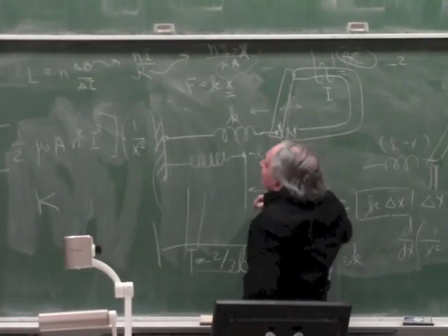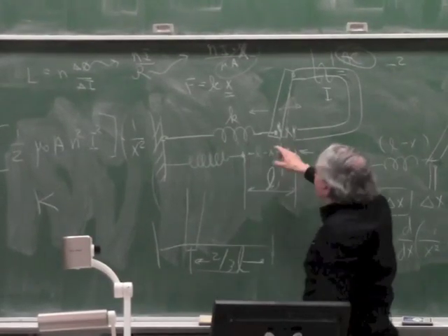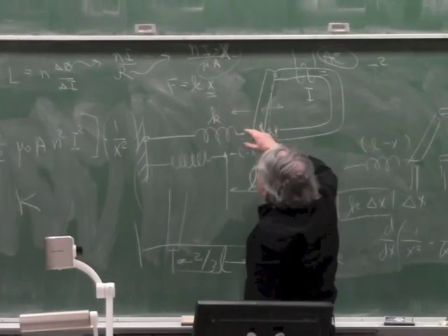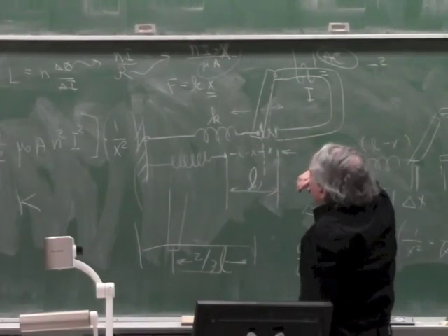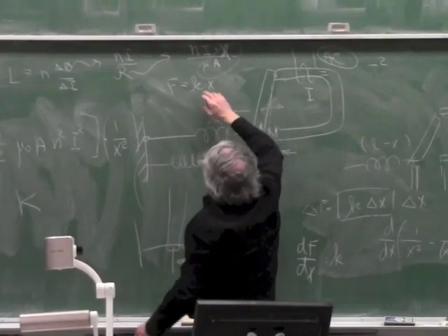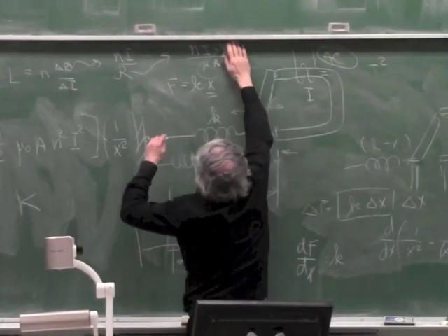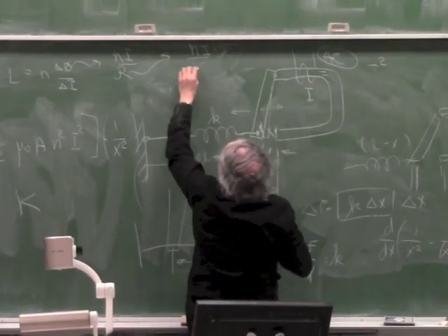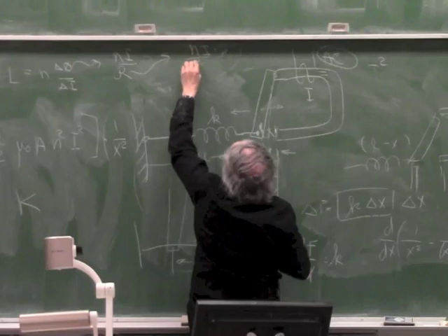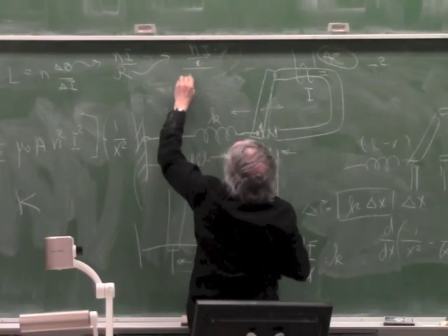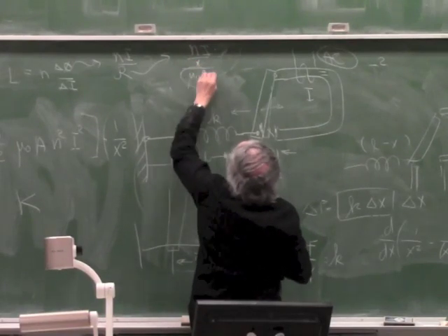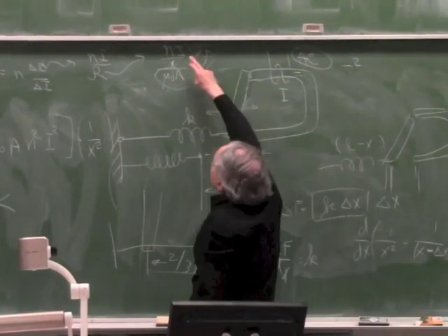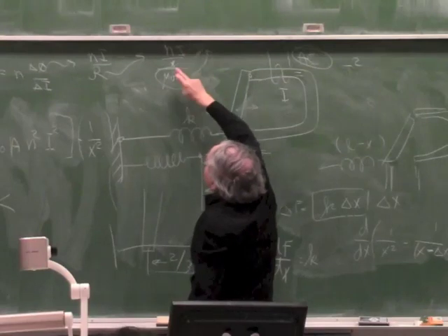So now the inductance will go up like 1 over x. Sorry, I have to divide by that. It's Ni divided by reluctance, and reluctance is x over mu 0 A, so mu 0 A goes to the top, so I'm getting the same thing you had one page ago, that it's Ni times this divided by x.